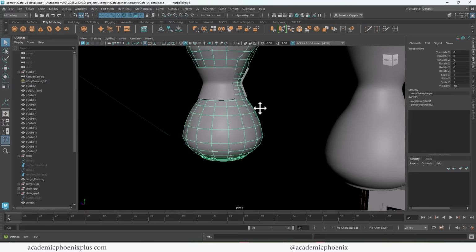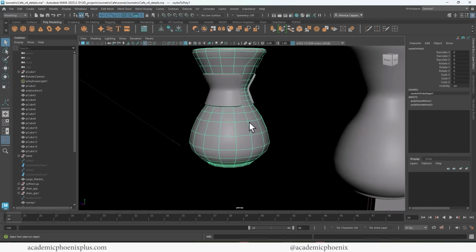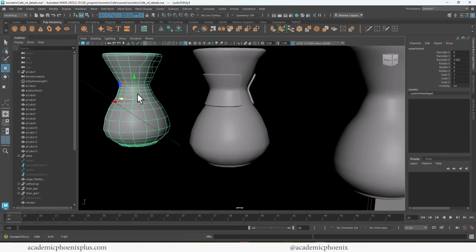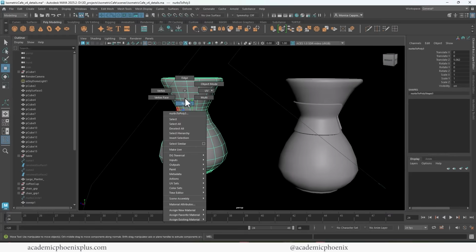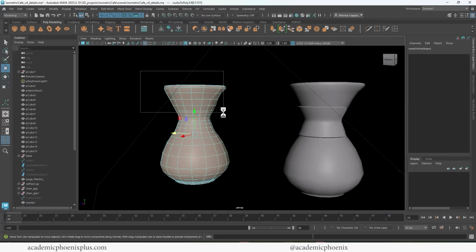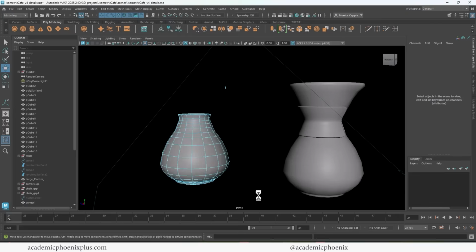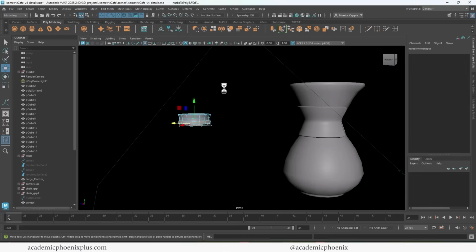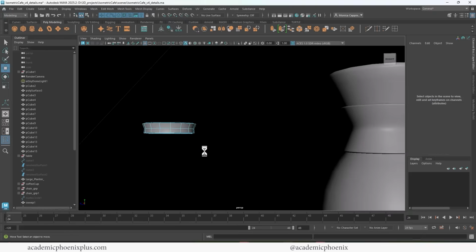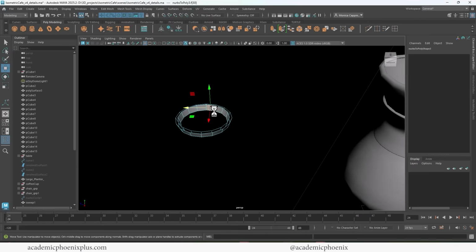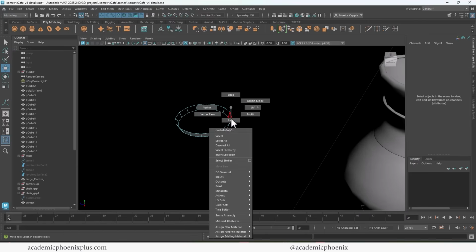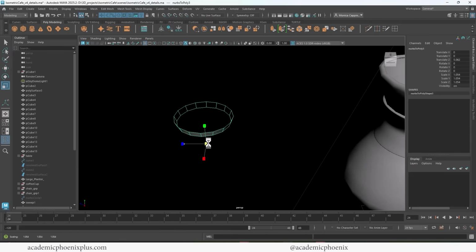There is a little bit of a rope around it, so again I'm going to use this, Control D. Why reinvent the wheel when it's already there and it already has the shape and everything? So I'm going to go ahead and delete these guys. Don't forget all these faces. And honestly, I don't need that much. I need maybe just a row. Delete this part here. Probably needs to be a little bigger, so let's go ahead and center that pivot, make it bigger.